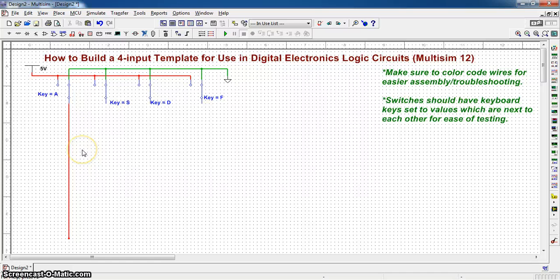I'm going to change the color in a minute so that when I place my other parts, everything is spaced nicely. So I'm going to do the same on the other wires here, simply dropping a wire and double-clicking when I get to the bottom. You can always extend wires from here by simply clicking from the end of the wire, which has created a node, extending it further and double-clicking to place your wire.